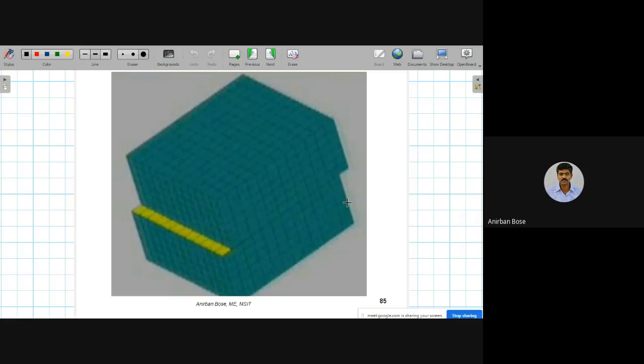You know how we do the plastic deformation, we apply forces, and then it is possible to change the shape of the material. So when we are making the permanent deformation in the material, basically we are giving the external mechanical force or the thermal energy. We are giving some energy so that the dislocation line can move within the material.